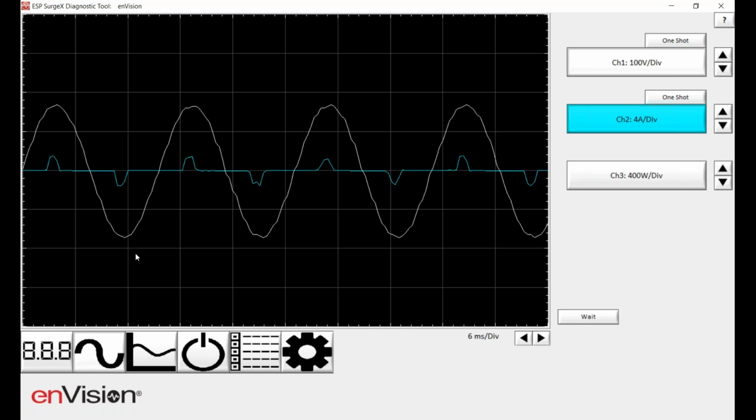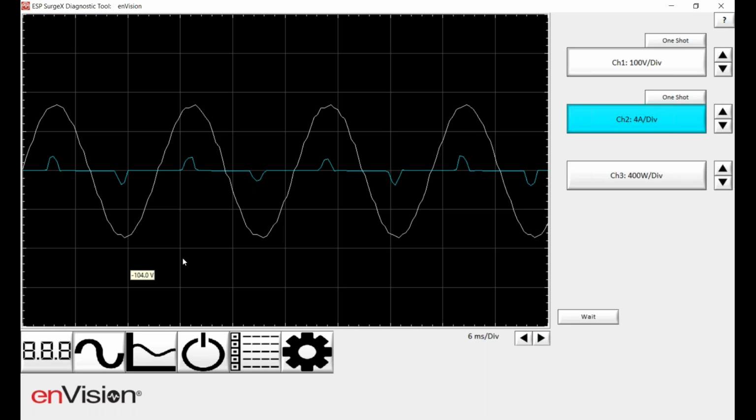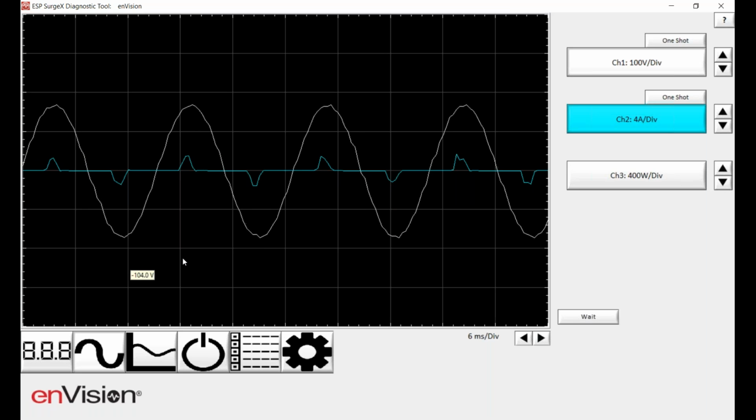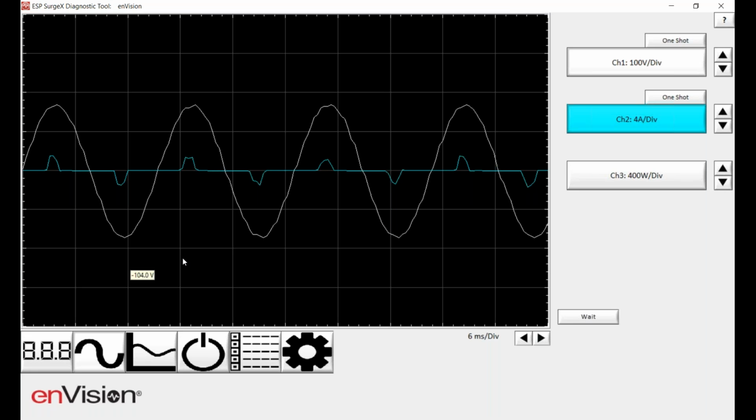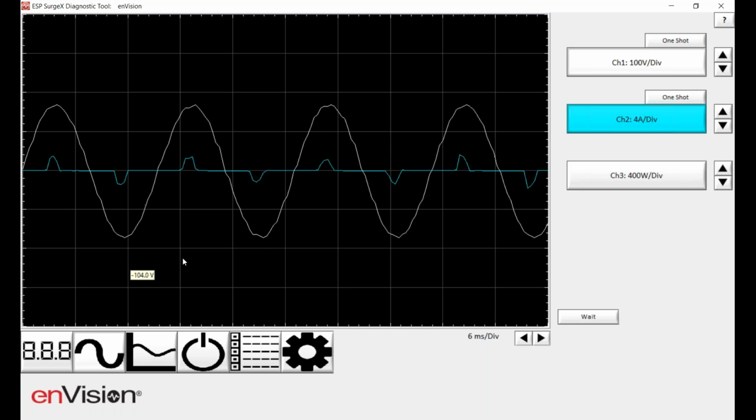So hey Vince, yeah? I want to make a comment on that, and I think this is something that gets kind of missed a lot of times, right? A lot of your big equipment that has switch mode power supplies will have what's called power factor correction built in, where the current draw is more sinusoidal and follows the voltage waveform and is not as much like this where it's only pulling in the center at the peaks. But if you have a rack with a bunch of smaller gear and it's all pulling current in a profile similar to your laptop here, it's all going to add up, and it's all going to be trying to get power only when the voltage is at a peak, and you'll see it flat topping and pulling down more and more.